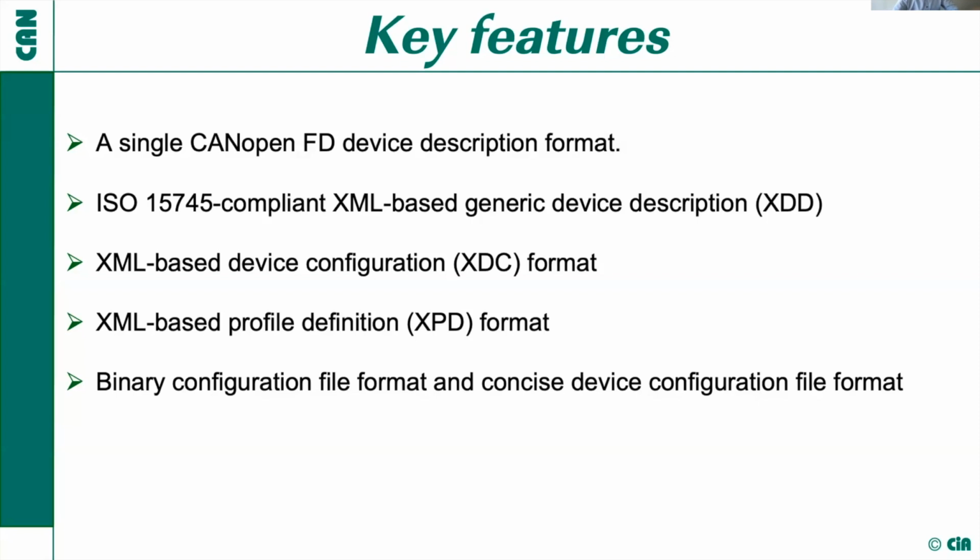As I said, classic CANopen has already a fully fledged XML-based device description, which was a modular, multifaceted one, but too complex for devices and systems designed many years ago. Nowadays, the power consumption, production, and capabilities of even microcontrollers and industrial PCs have grown ever since. And if we consider also cloud-based applications, XML-based device description is the way to go.